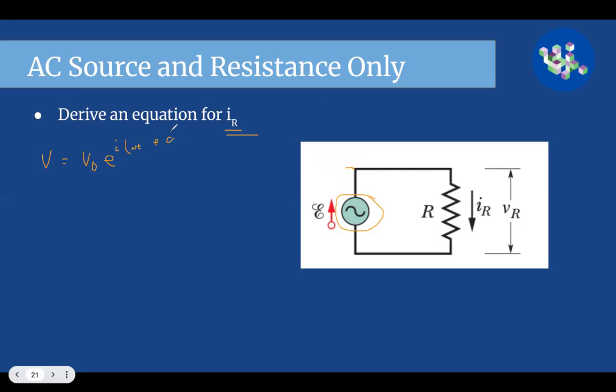It's really helpful to think of voltage as a complex exponential because this way you can take derivatives, and you'll also find that is how we're going to get complex impedances, because complex impedance is a complex number. So we'll express voltage and current as complex numbers.